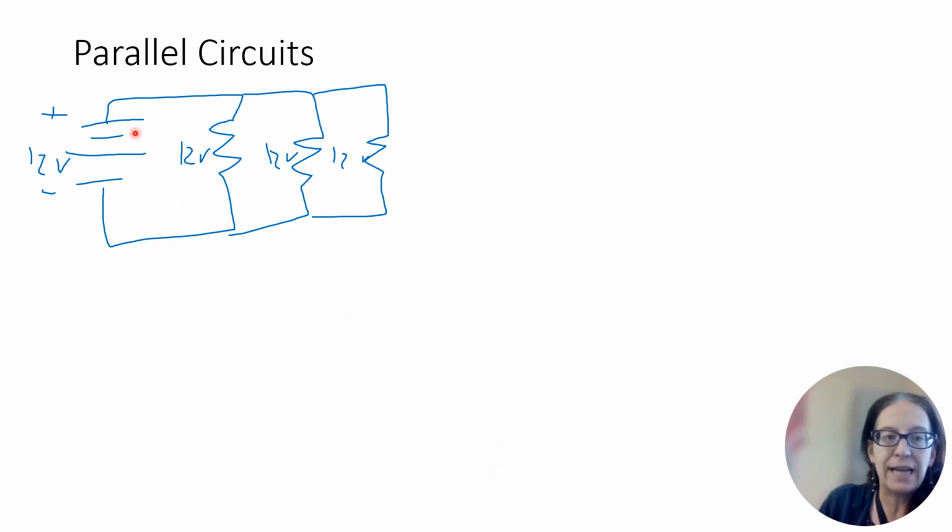So this kind of circuit is what would be known as a current divider. It will take the total current and split it up over the different resistors. It's a similar thing: with more resistance you have a bigger voltage drop, but in this case, the more resistance, the less current. So you can think of it again like a waterfall or a stream. The more resistance you have in a particular path, the less current is going to want to go through it.